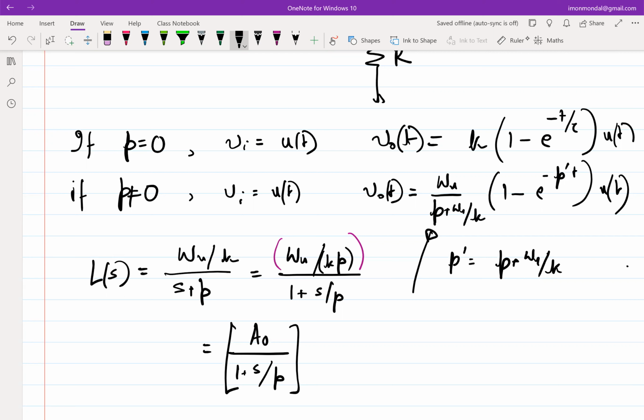Okay. So now let's hop back to our real integrator system, and we'll just use the same logic as we did just now. In real negative feedback, the only thing that differs from the ideal is that you have some DC gain. Everything else remains the same. If I ignore the phase for the time being, my omega u loop is still omega u over K, and my feedback still works below omega u over K, and it doesn't work above omega u over K.